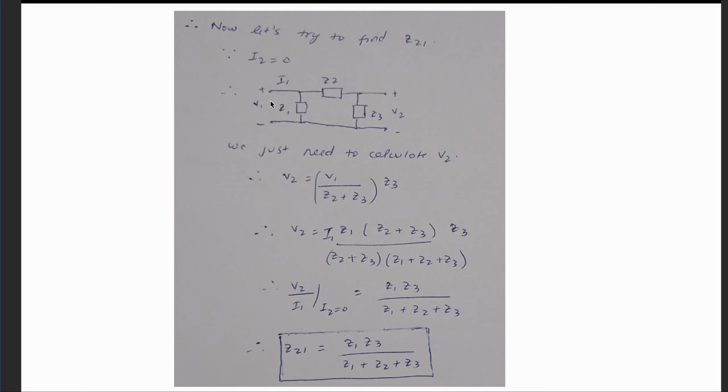So basically you know voltage V1, and from there you can calculate the drop of voltage across this Z3, which is the port 2 here, because I told you that current is getting divided. And how the current gets divided, you know that I is V over R. Because these two networks, Z1 and Z2 plus Z3, are in parallel, the current going into Z1 will be V1 upon Z1, and similarly the current here will be V1 upon Z2 plus Z3, right?